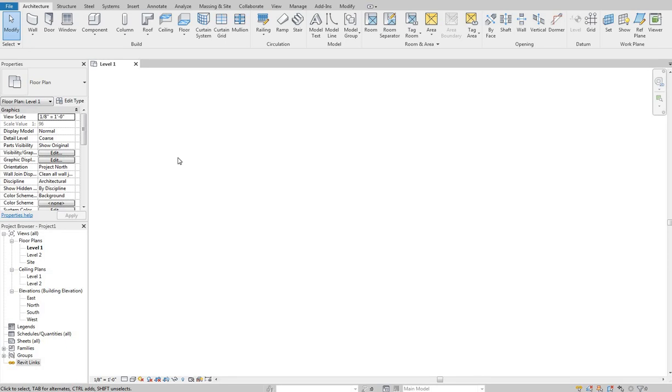Before we get into that, one thing to note that new Revit users also often run into is they get into a 3D program for the first time and they feel like they need to model everything in 3D. They want this immaculate model that has every detail modeled out, and that is just a horrible way to go about building a model like this, simply because it's going to get really cumbersome, it's going to be a huge file, and you're not going to use 50% of those 3D details that you've actually created.